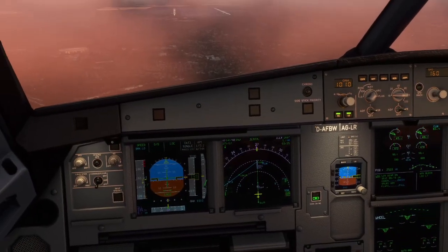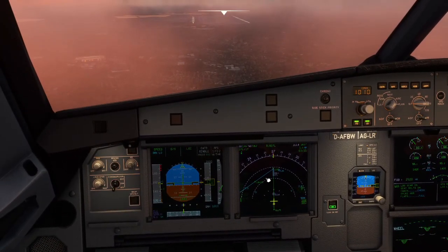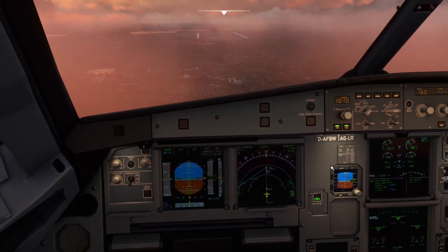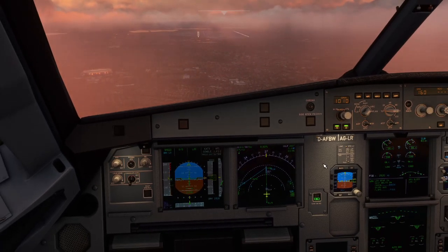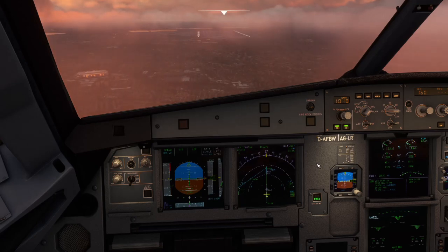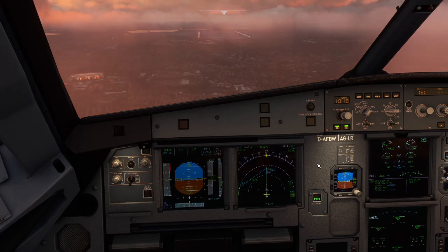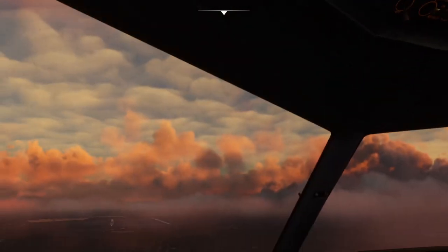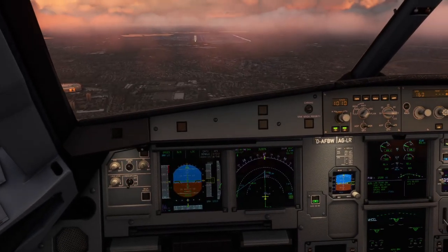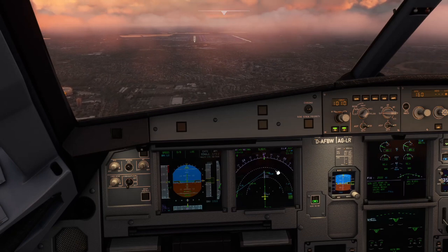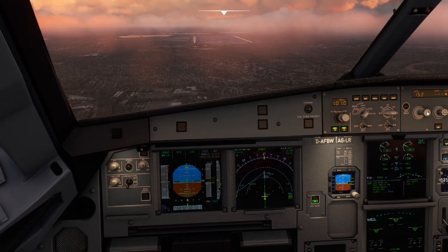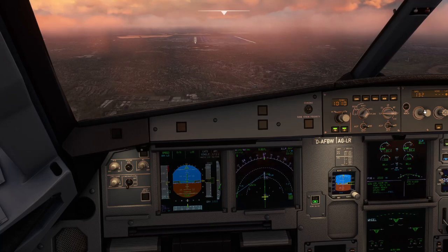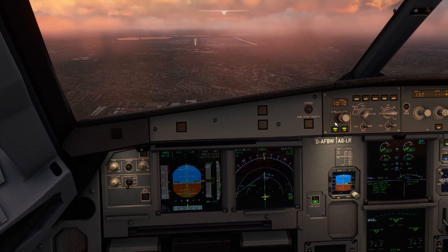We set our VAPP 132. You can put it back in managed speeds if you like. I'm going to manually set 132. You can see the landing checklist has come up. Only a couple items left to go. We can tick one off now. It's an easy one. Okay, I'm going to trickle my speed back for 132. And I'm selecting flap full.